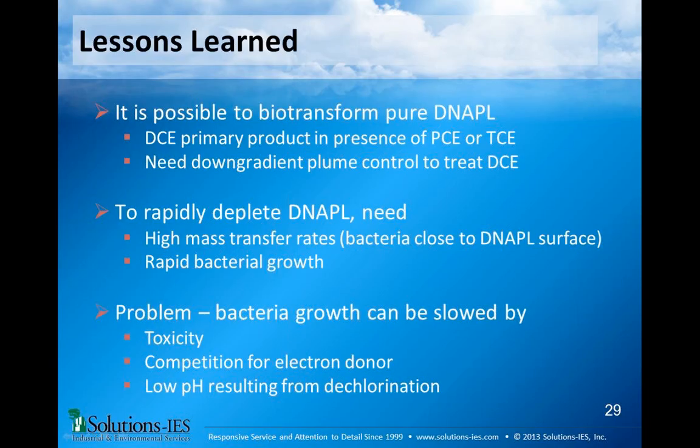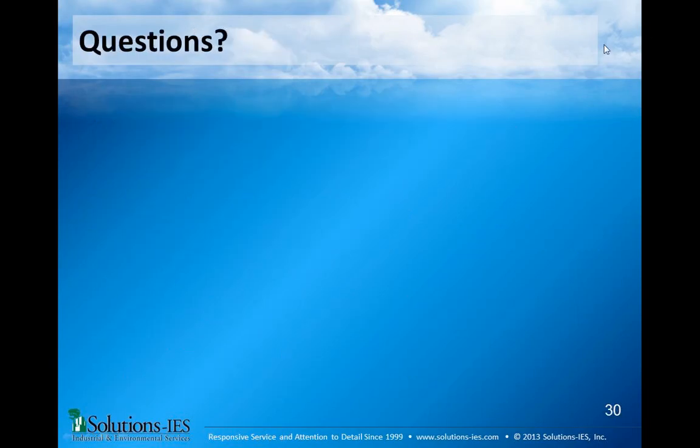So now we're down here at a pH of about 6. 6 is not good, but it's not nearly as bad as 5.5. Plus, at this point there's virtually no PCE in this column anymore. So we've dramatically reduced the PCE toxicity by the time the pH buffer starts to get depleted, and so clearly the DCE production is continuing to increase here.